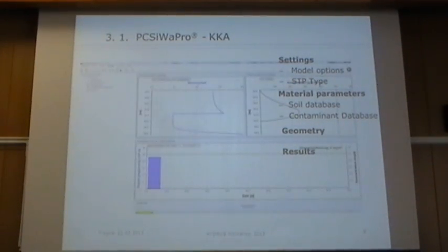And then you run your program, and here you get an overview of how your water content is behaving during the simulation, and how the concentration is looking during the simulation. And because in Germany we have a drinking water law which tells you the upper limit of your contaminants in the groundwater, we introduced a limit for each contaminant. So you will know during the simulation if your concentration is beyond the legal limit or not.